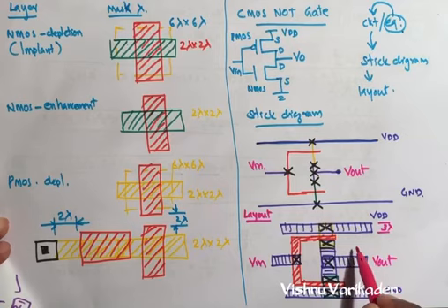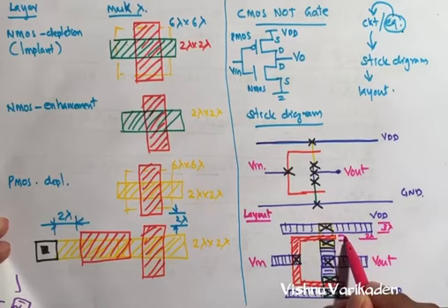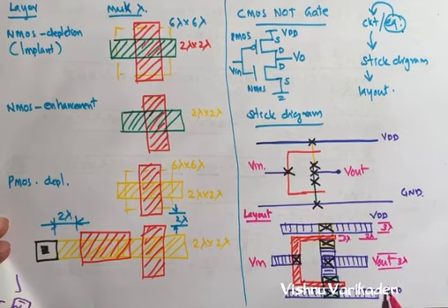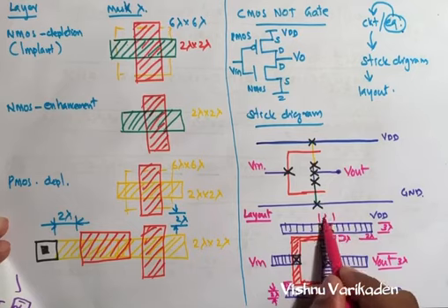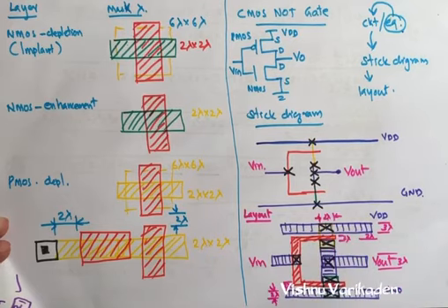Also, in between metal and the polysilicon is 2 lambda, and the thickness of this one is 2 lambda. Also this one is 3 lambda, this one is 3 lambda. Also this one, metal to polysilicon to metal, is also 2 lambda. This one is 2 lambda conductor.